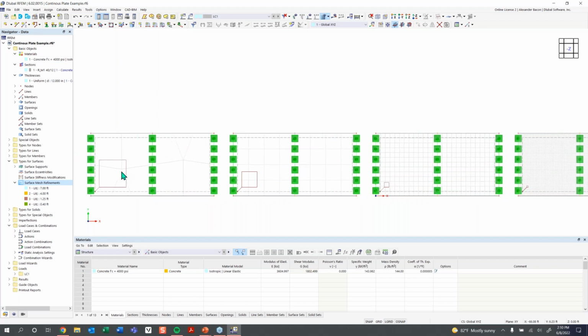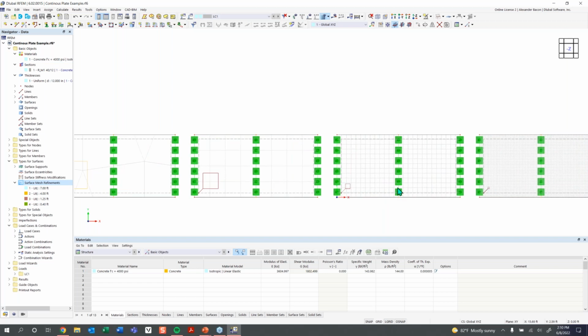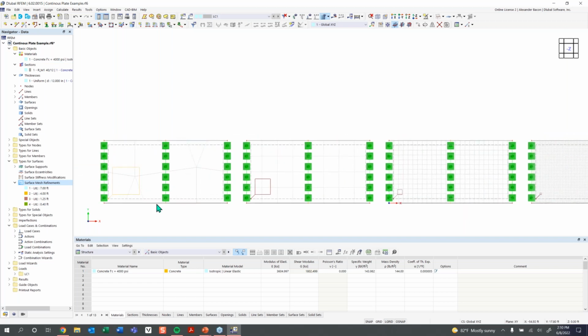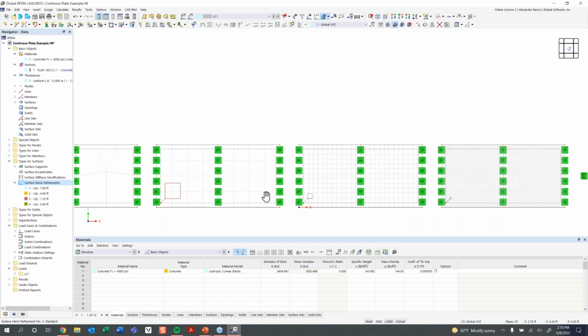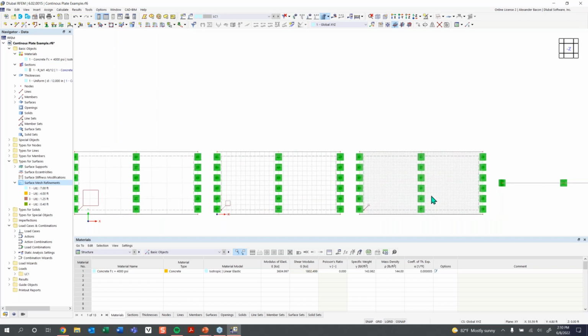This first size was 7 feet, and you can see it goes from 4 feet to 1.25 feet and gets smaller and smaller. So on this first surface here, I would expect very inaccurate results. And as we move from left to right, the quality gets better, and I would expect very accurate results from surface 4 here on the right hand side.